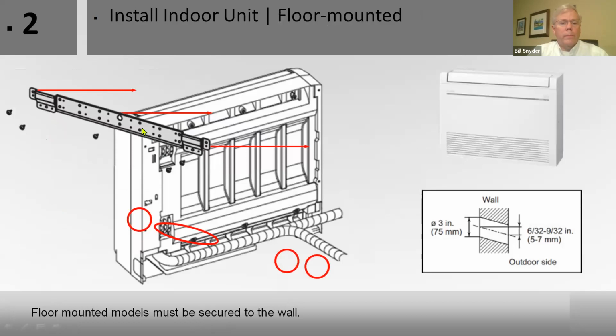The wall unit, this is a floor mounted, it says, but it's actually a low wall unit. This thing here mounts on the wall, and this unit hangs on it, and this is where your piping comes out. You don't want to drill into the sill plate. You have to have it up high enough. So as long as you're up, typically above your woodwork along the bottom or your mop board, then you should be okay on this particular unit.